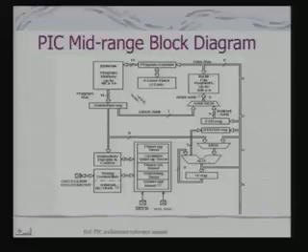Now there are two kinds of bus structure you have found here. One is the direct address, which goes in through the address multiplexer to select the registers. Here you will find that the 8-bit data, as part of the instruction, is coming directly to the multiplexer by which it is fed to the ALU. Now why is this bus there? To enable immediate mode addressing, that is, when the data is part of the instruction.